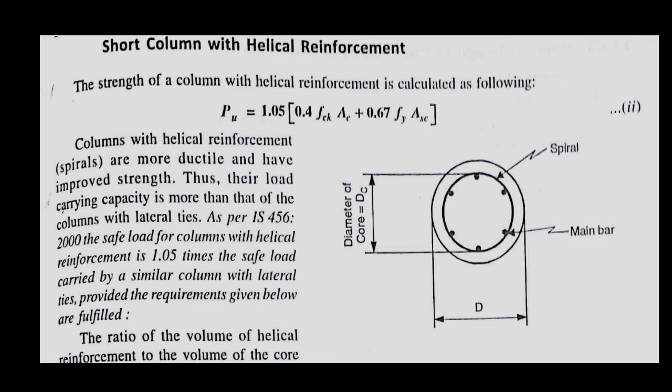Before we read it out, let's check the IS code consideration. For helical reinforcement, the IS code consideration is given in clause number 39.4 of IS 456 2000.